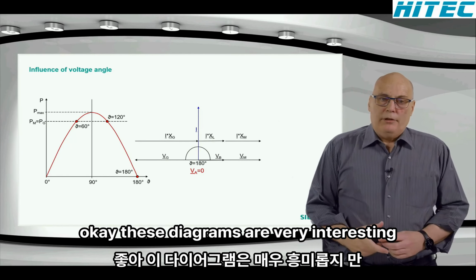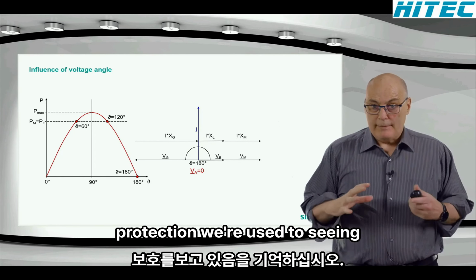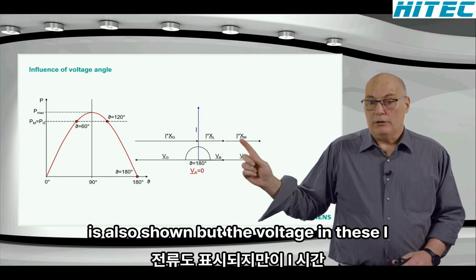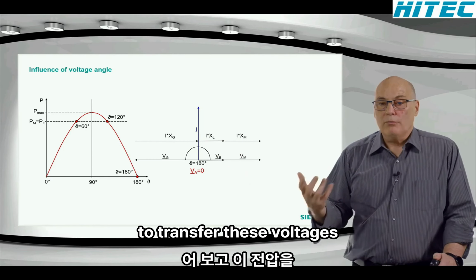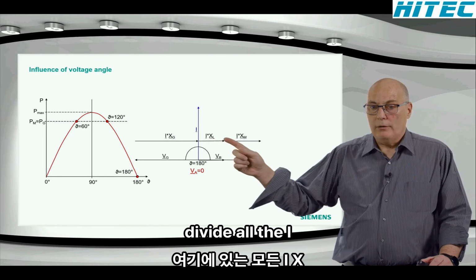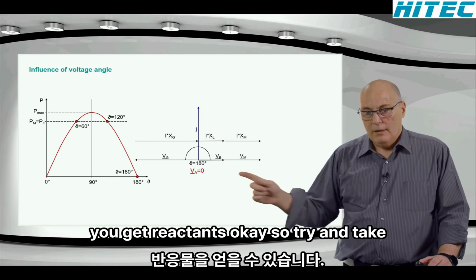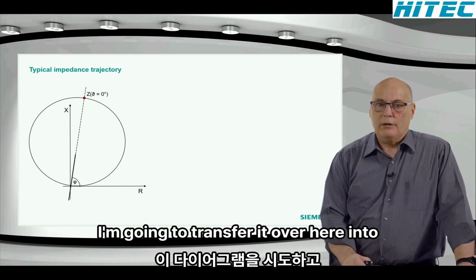Okay, these diagrams are very interesting, but remember we are looking at the distance protection, and in distance protection we're used to seeing impedances. These are voltages, remember, real voltages. Current was also shown, but the I times Z are also voltages. To transfer these voltages into the impedance plane, you simply divide all the IX voltage drops here by the current, and then you get the reactance. So try and take this diagram that we have here now, and I'm going to transfer it over here into